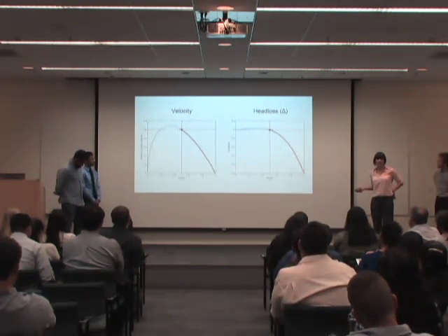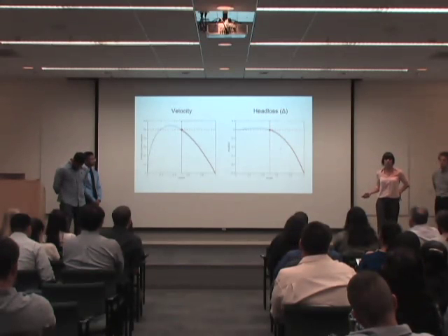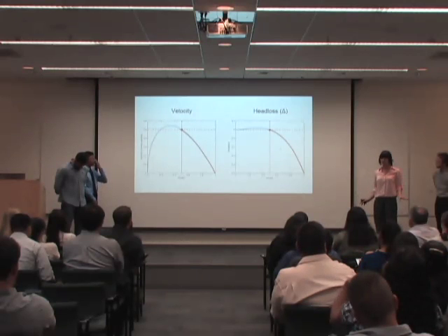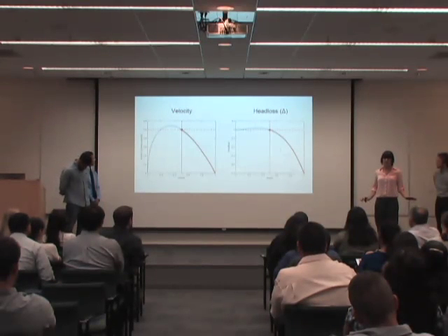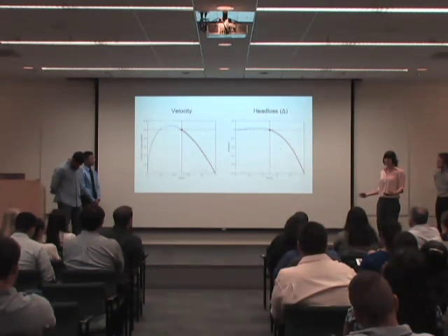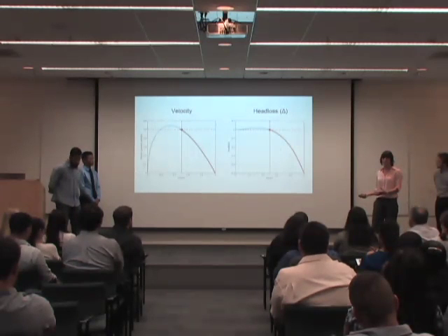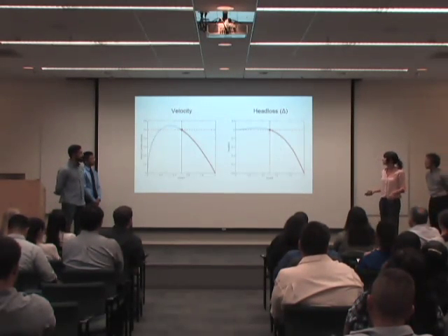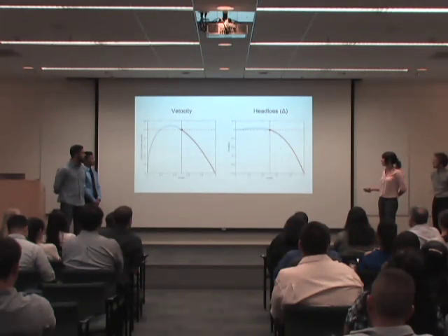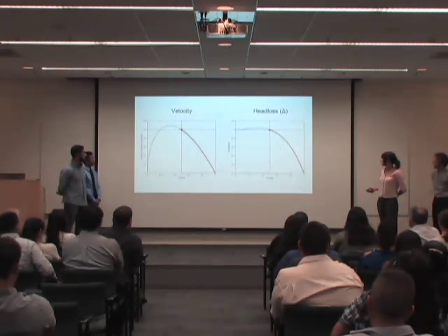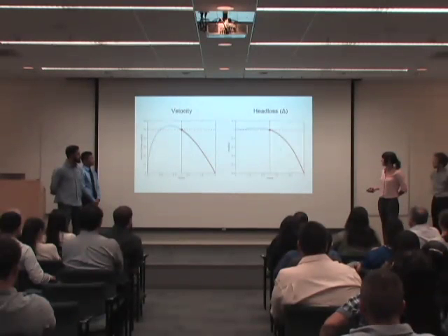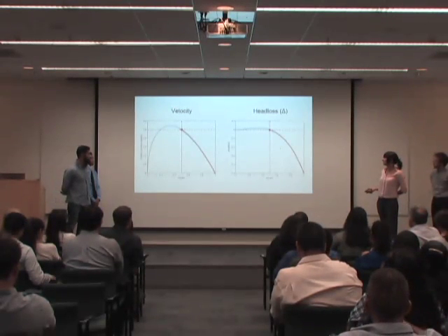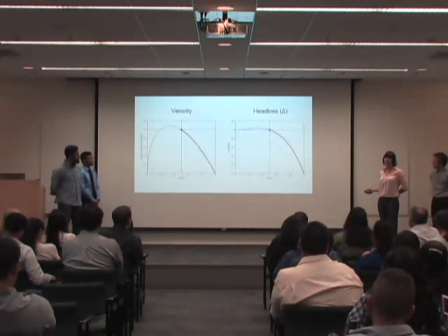Now, head loss again is the energy lost through friction and mixing, and it's important to know that it must always be positive. It cannot be negative. Negative energy means that you are gaining energy from something that isn't there. So we discovered that we must have a height of gravity current of 0.5 or less in order to keep the head loss positive.